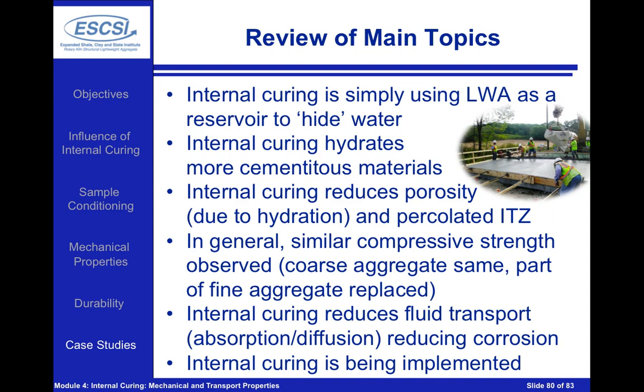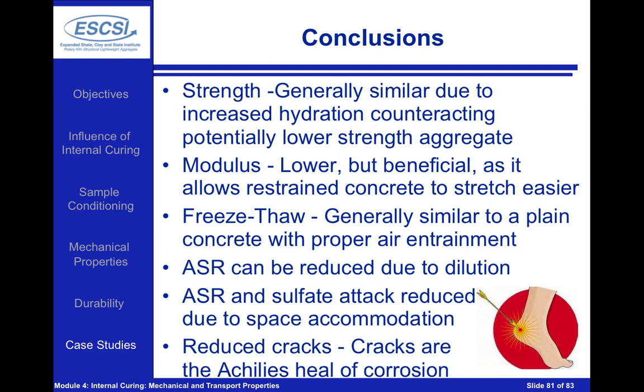The final takeaway is that internal curing is being implemented, and when it's being implemented on bridge decks, very positive things are being noticed with a reduction in the overall cracks that are forming in those systems, and very similar, if not improved, transport and strength properties are occurring in those cases.